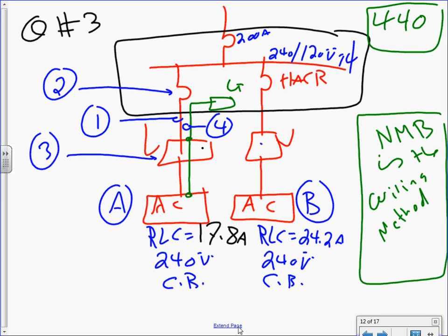conditioning. The special thing about AC units, guys, like we talked about yesterday, every time you have hermetic compressor motors coupled together, built together to make a system, they function differently, and the code treats them differently. Even though they have motors in them, the code refers you to Article 440 because of their characteristics; they behave differently and have different characteristics enough to distinguish them from standalone motors.